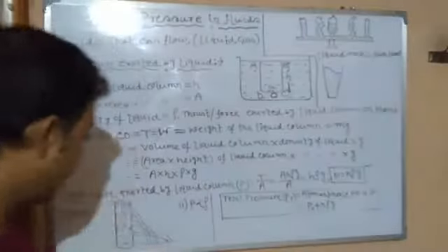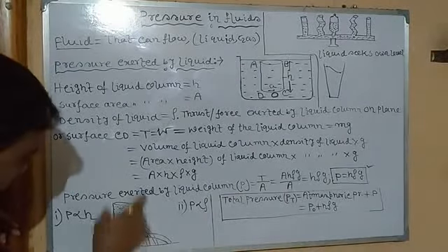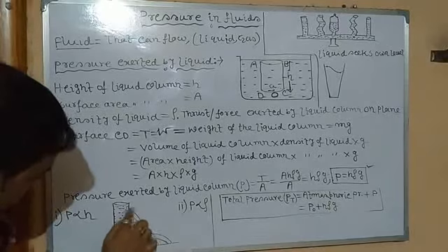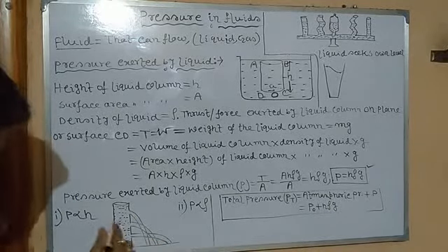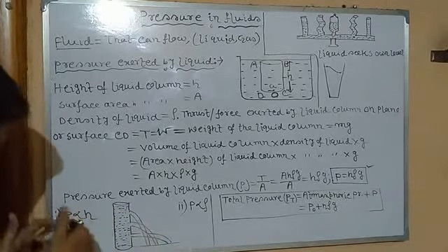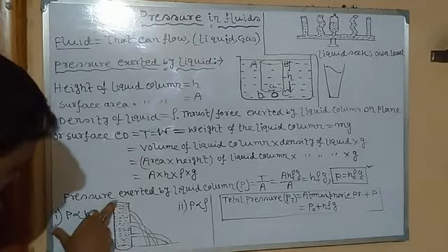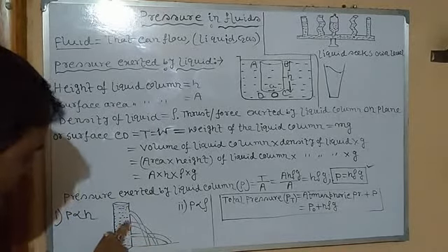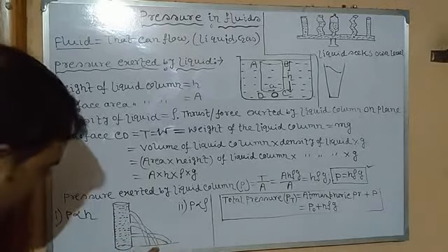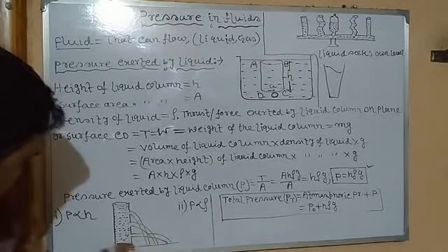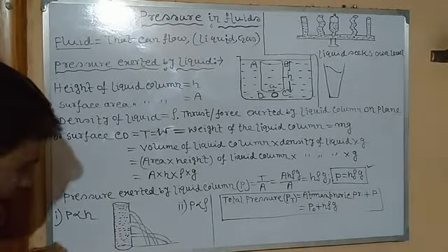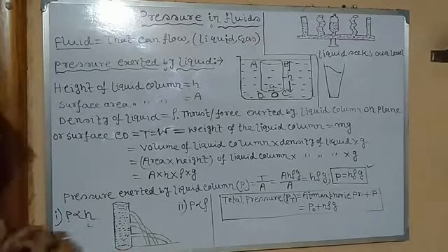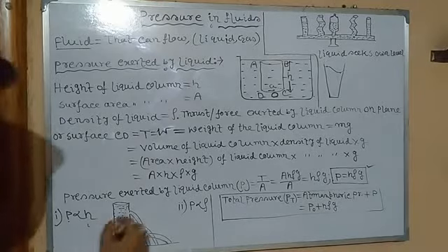That can be easily demonstrated through a very simple example. You can see there is a cylindrical vessel and it contains some water, and we have made three holes in it. From the point at the extreme top, the water will flow and traverse a small distance, whereas the water which emerges from the middle hole traverses a slightly greater distance, whereas from the point at the extreme bottom, the water after emitting travels a longer distance, because pressure is directly proportional to the depth, the height of the liquid column from its free surface.